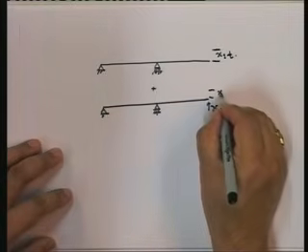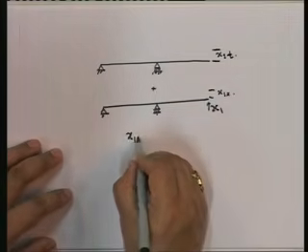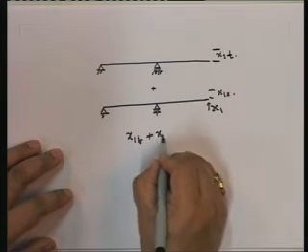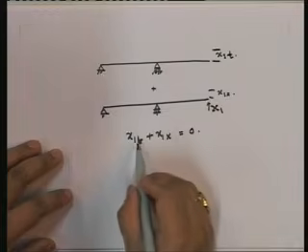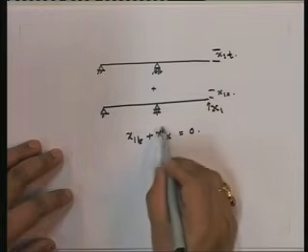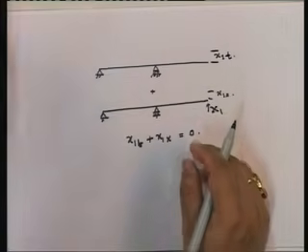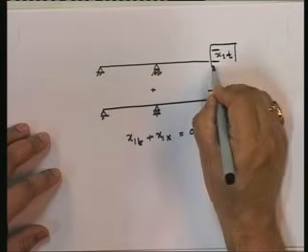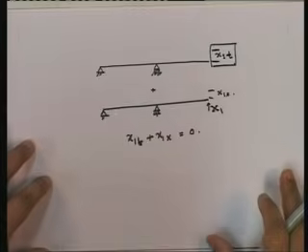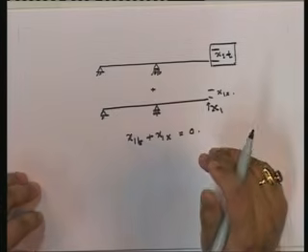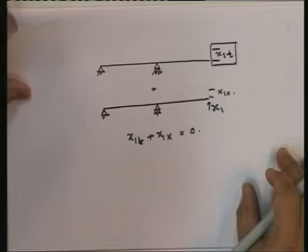And find out this displacement x1, and the compatibility condition is x1 of t plus x1 of x equal to 0. So note that if this is equal to 0, this is equal to 0, and this is equal to 0, then x1 is equal to 0, and if x1 is equal to 0, there are no forces in the members and there is no effect of the temperature, differential temperature. So the whole thing hinges on whether there is an x1 of t due to the differential temperature, and that is our whole focus over here. Okay, so let us see what happens.